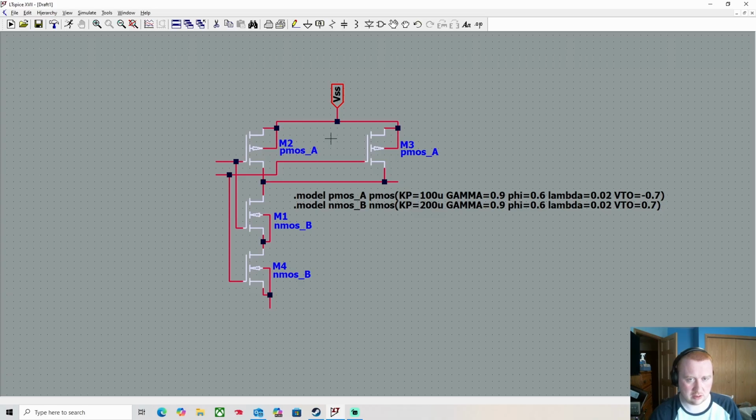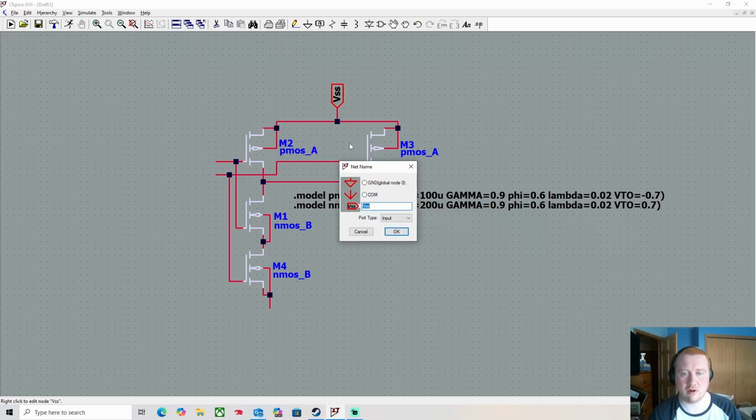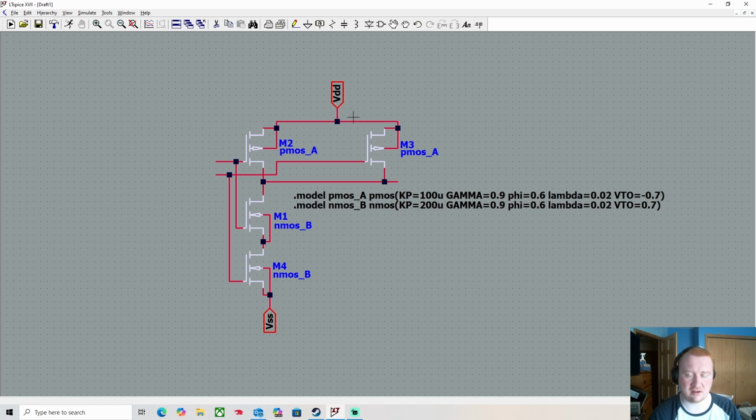No, sorry. That's wrong. Is it? No, hold on. Give me one second here. Sorry, no. It's VDD. I always get them mixed up. It's been a while since I've actually seen a technical data sheet with the power, but yeah, VDD and VSS is the proper distinction. So I'm going to call this one VDD, and then I'm going to need the negative sides. That's the VSS. Again, I guess we can call it an input, even though these are technically bidirectional in some way.